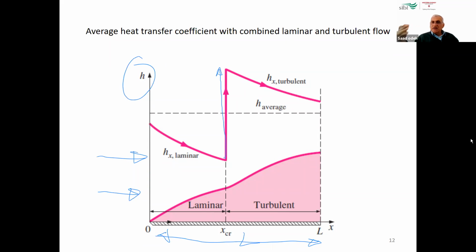To make it in simple form, with the turbulent flow, we have more mixing. The flow starts to be disordered, highly disordered. Because of this, more heat transfer will take place. And that's why H is higher. Higher H causes more heat transfer.